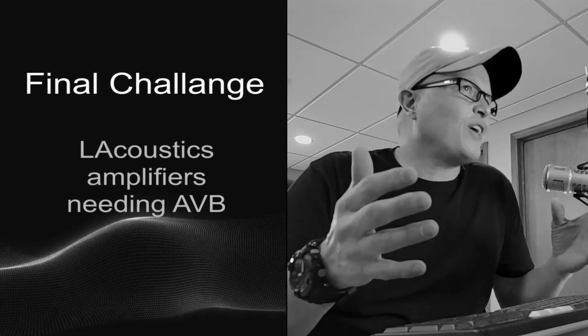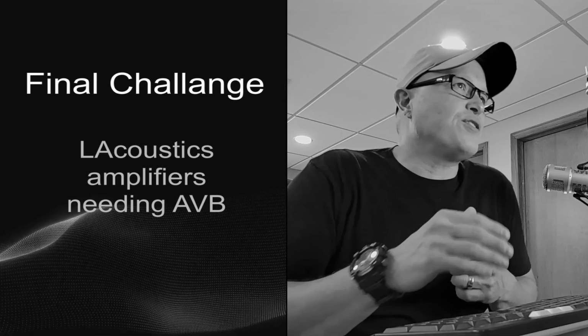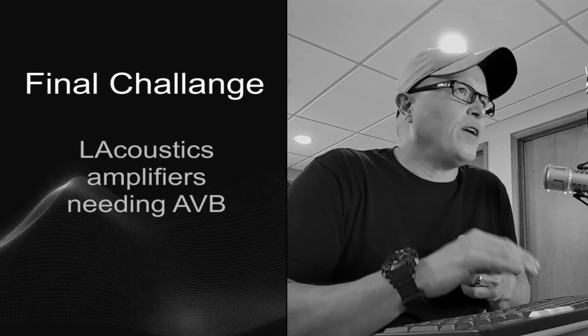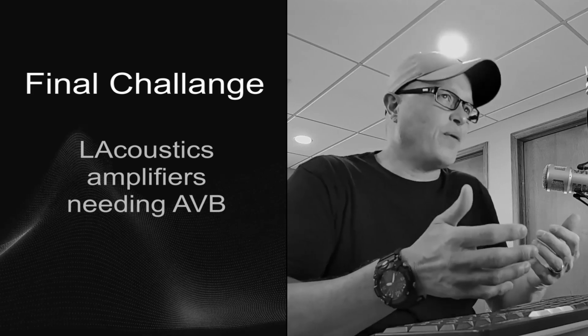Now, the final challenge was needing the digital audio to be in the AVB audio format once it hit the L-Acoustics amplifiers. We had several LA4X amplifiers and also the newer LA7.16 multi-channel amp. The only way to hit the multiple channels inside that amp with different feeds was by using AVB. With AVB, it's capable of receiving up to 16 separate audio feeds, one for each channel if needed.